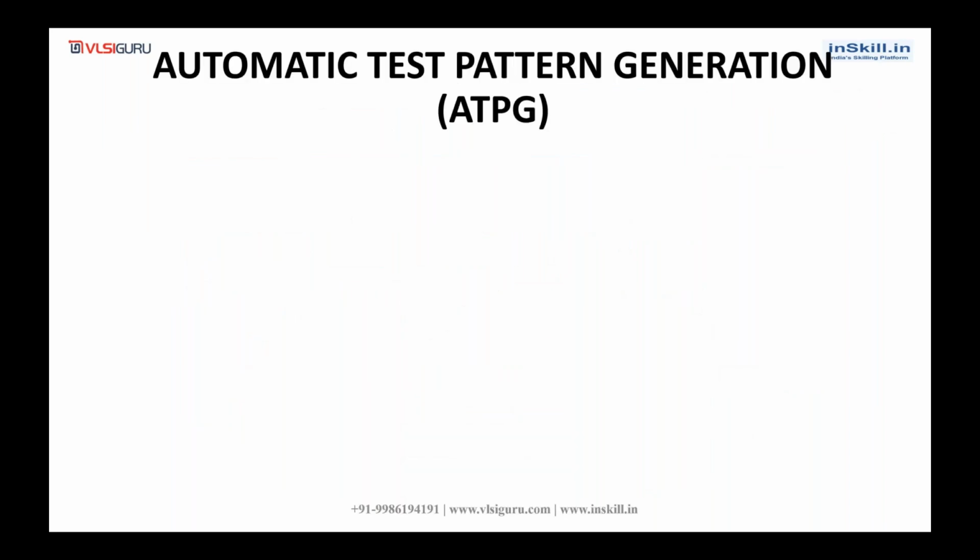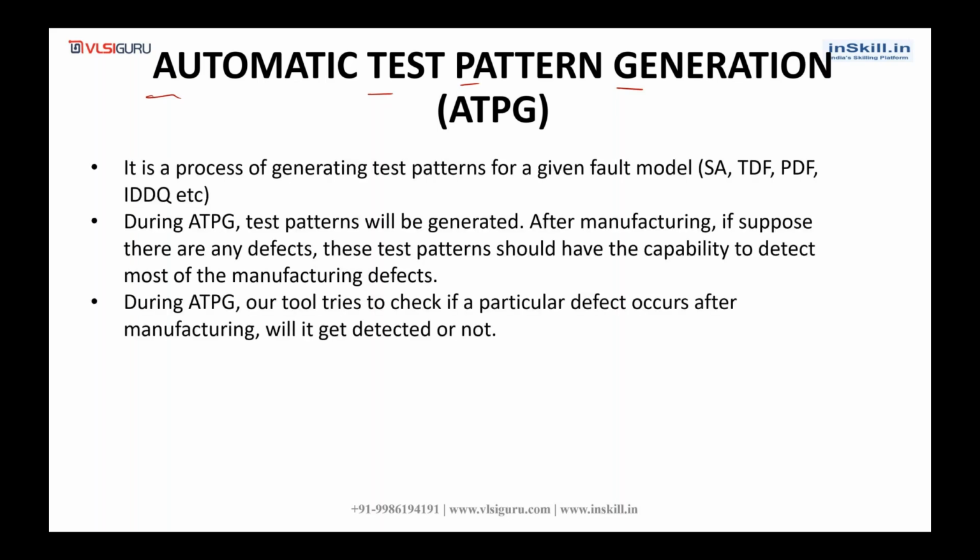Next is ATPG. ATPG is automatic test pattern generation. As its name suggests, it is a process of generating test patterns for a given fault model. The fault models are stuck-at, TDF (transition delay fault model), PDF (path delay fault model), and IDDQ fault model.